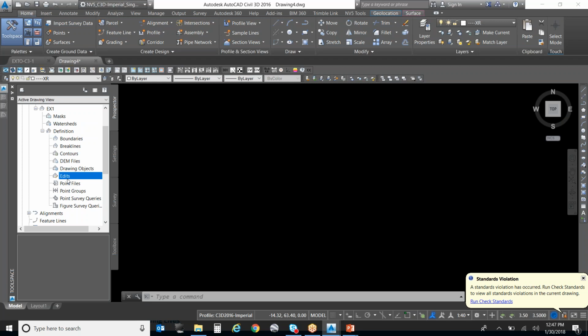You also know that if you change the point group later, it also edits the surface. Okay? So that's why we're suggesting you make a separate point group and you keep it as is. If you edit that point group, you've edited the surface. Which is helpful because it's then dynamic, so you don't have to recreate this thing. It's just, hey, rebuild and you're good. When you're first building it. But later in the job, you're not wanting to change that existing surface.